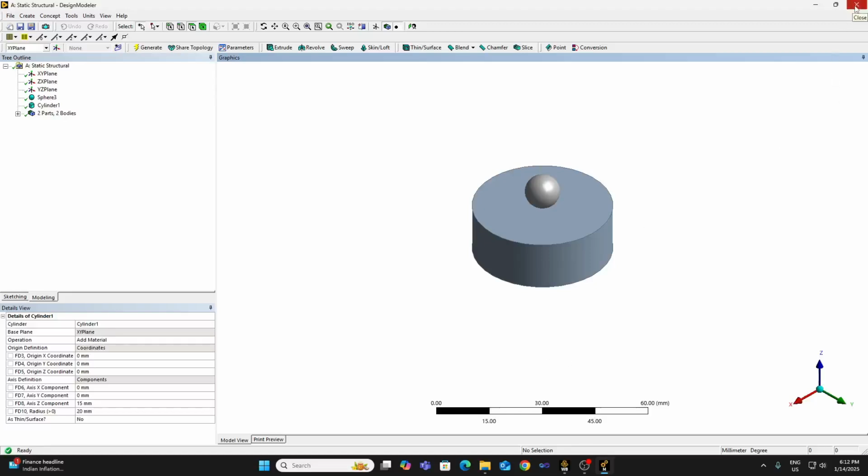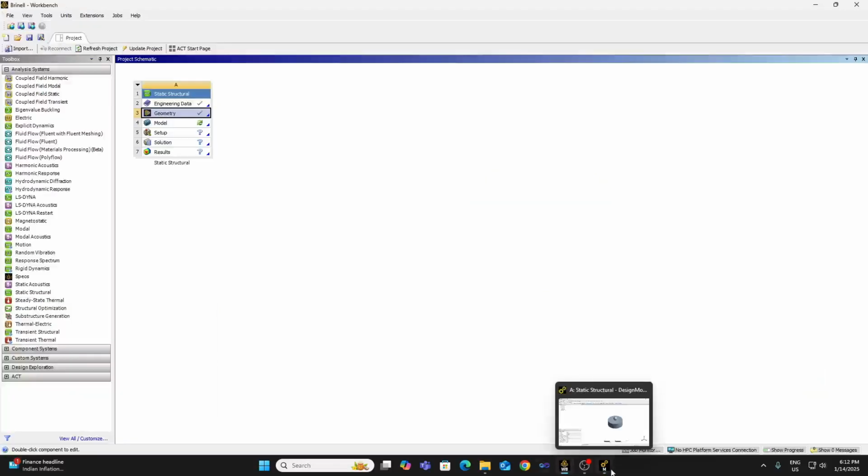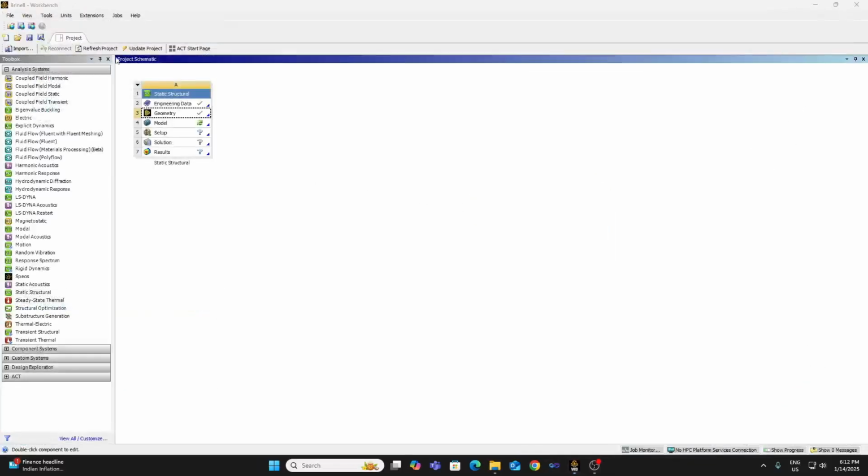So we do open the mechanical window, and there are a few things that we need to learn there. So I've closed the geometry, and I'm also saving the file. Now let me move on to modeling. So this is where we would give the mesh control. We'll define the contact, we'll define rigid body, we'll apply the forces, put the boundary conditions and other things.